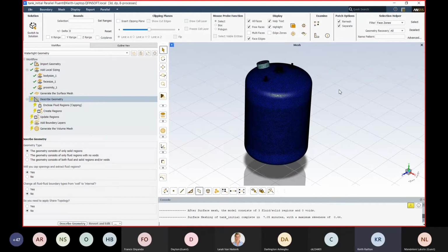So you can explicitly do a mesh convergence study where you control it and just keep reducing these local sizings and your mesh sizing until you get a converged solution. Alternatively, as I said, you can straight off the bat use the mesh adaption, where it will adapt automatically while it is solving.